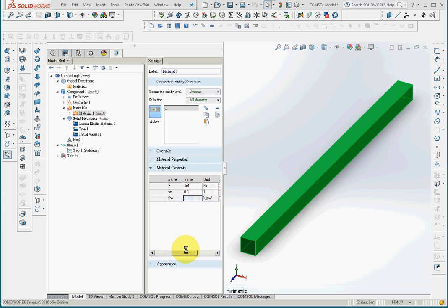And density is not necessary right here, but it is required, it seems. So I go ahead and define the density for steel, which is 7850 kilogram per meter cube. But generally, density is not necessary in a static analysis. In dynamic analysis, density is required. But now I might as well enter the numerical value for density, because it might be required in the software, but it is not necessary for the implementation of calculation. So I have defined the Young's modulus 3 times 10 to the 11th and the Poisson ratio of 0.3. So I finished with defining material. This is the second step for CAE analysis.